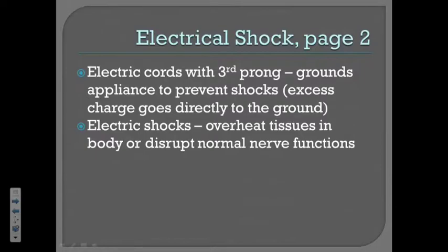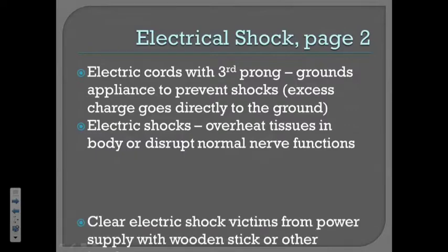So if you ever see someone who is actually being shocked, you do not need to go grab them and pull them off, because you will become shocked too. Your muscles will contract, and you'll just hold on to them tighter, and you'll both be getting electrocuted at the same time. So what do you do if you see someone getting shocked electrically?